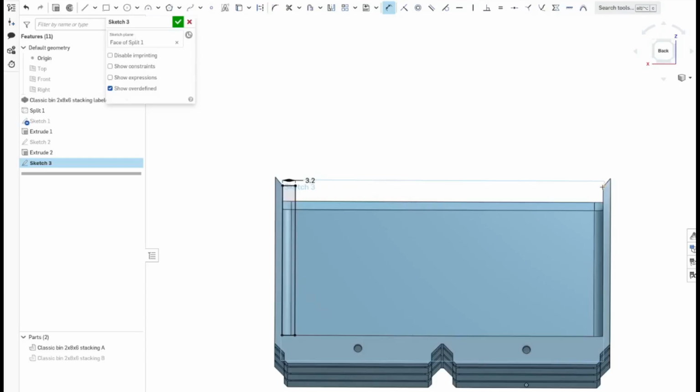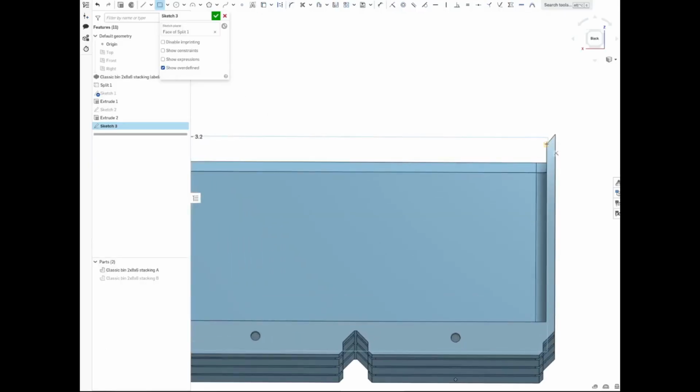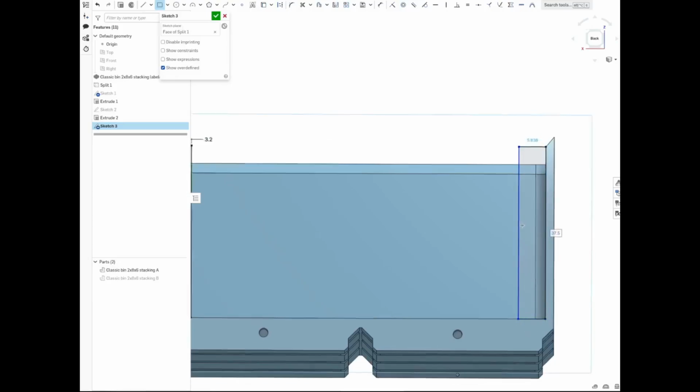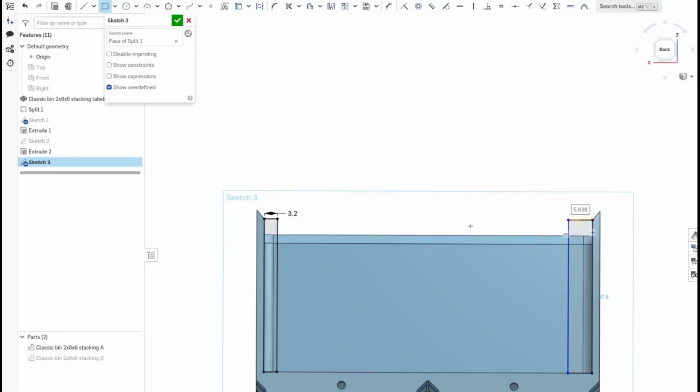and the same thing we'll do on the other side. So we'll click on the corner rectangle over here, then again click on this point and drag it down until this horizontal line is highlighted and click over there. Then we'll keep the dimension of this width and this width the same. So for that, click on the escape key and select both the lines, this line and this line. You can click on the equal sign over here, or you can press the E button on the keyboard. So this will be equal in width.